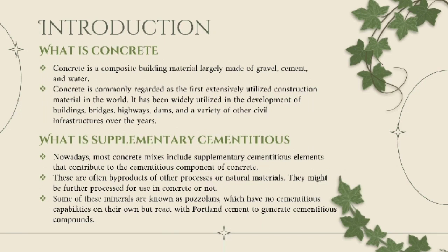Next, moving on to supplementary cementitious materials. Nowadays, most concrete mixes include supplementary cementitious elements that contribute to the cementitious component of concrete. These are often byproducts of other processed or natural materials. They might be further processed for use in concrete or not. Some of these minerals are known as pozzolans, which have no cementitious capabilities on their own but react with Portland cement to generate cementitious compounds.